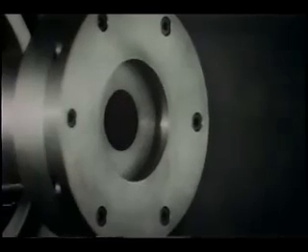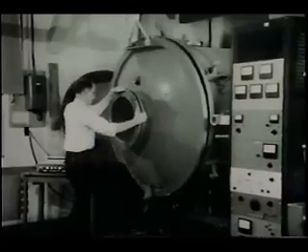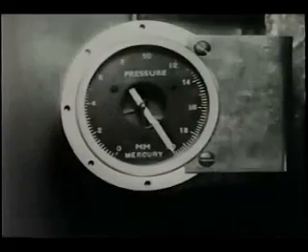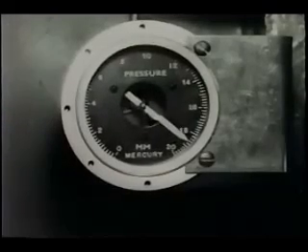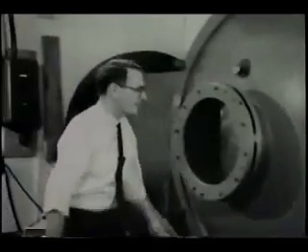We use a freely expanding jet again. Here is the nozzle, which is large enough to be in continuum flow. The tunnel is pumped down. In order to see the flow in this tunnel, we use the electron gun to fire an intense beam of electrons across the flow to excite a fluorescence in the air remaining in the tunnel.